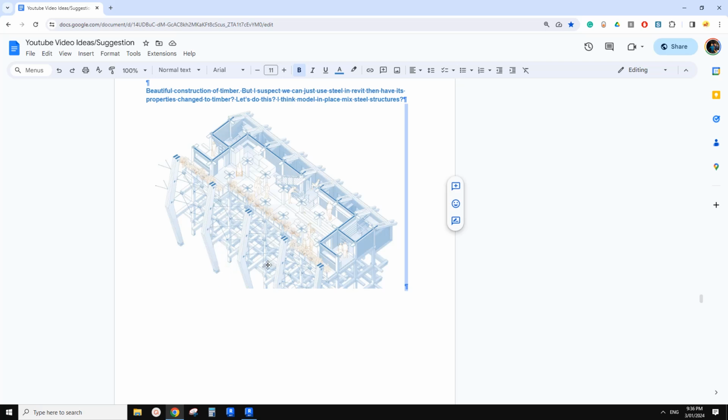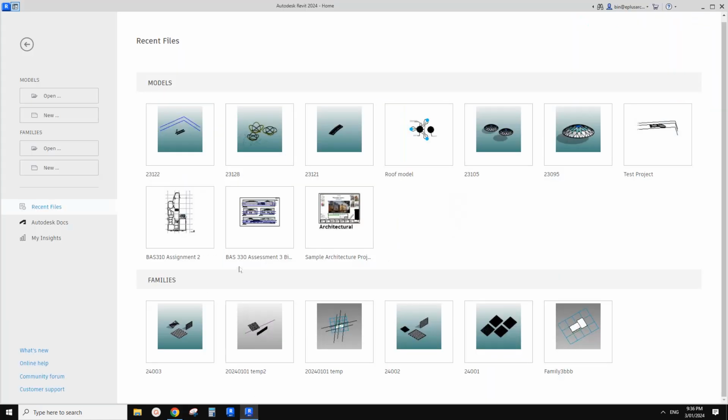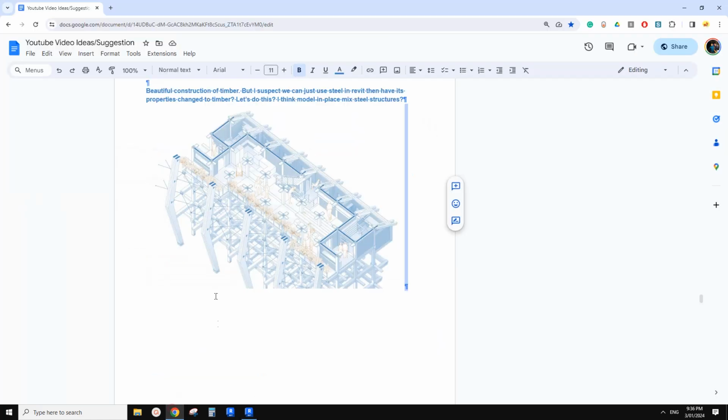We can use it just like a structural column. We can use a two level based family so we can change the top and the bottom. We can also make it parametric, so we can adjust the size on the base, at the top, and also the middle, and maybe we can add an angular parameter so we can adjust this angle as well.